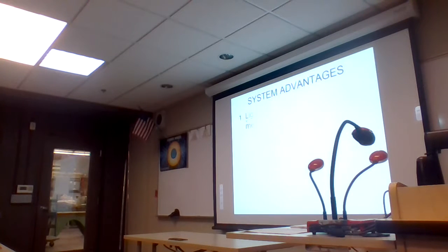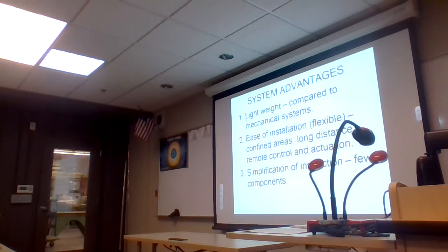Well, we do have something. We've got approved cleaners that have flash points a little bit higher than -50. So we use solvent quite frequently. It's still an approved solvent, but some of these things are, again, really dangerous because they flash off so quickly, or at least their flash points are so low.